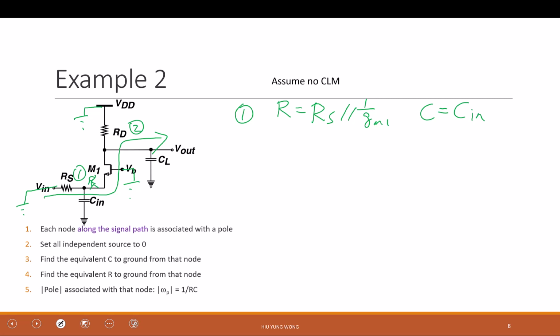We drew a circuit, the small signal circuit, applied V and then measured I. We solved the KCL, KVL, and we found out that V over I equals 1 over Gm. Maybe you forgot that, but it's not because I just gave you the equation. We really solved it.